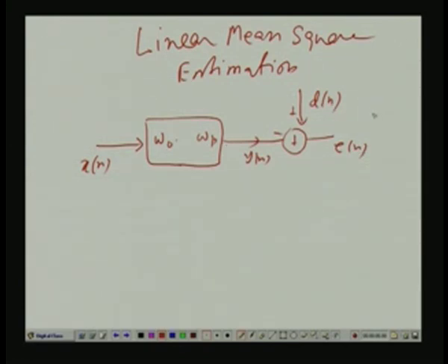So, you minimize it. Quadratic functions have one unique minimum or maximum. In this case, obviously it will be a minimum, because there is no maximum here; you can always deviate from your optimal coefficients and get more and more error variance. So find out for which coefficients the mean square value of this output error En is minimized. That will give rise to the optimal filter, which is unique, and is also called the FIR Wiener filter, named after the great mathematician and statistician Norbert Wiener.